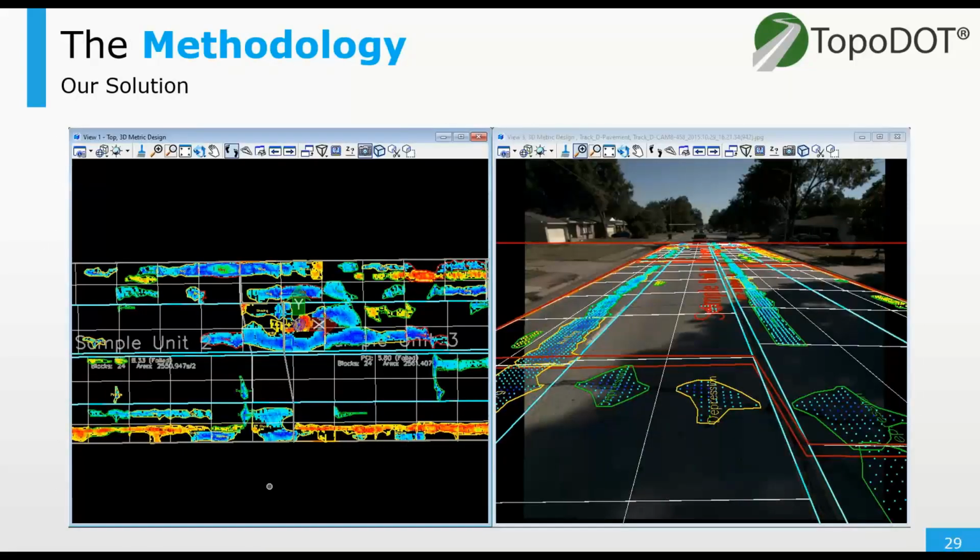So how do we accomplish this with mobile data? We're going to break this down into a few major components. How we sample and break the lane lines down according to ASTM standards, how we flag or identify the potential distresses, how we are finalizing the distress items through automatic and user-defined procedures, and ultimately generating reports. So we're going to break it down into those components there.